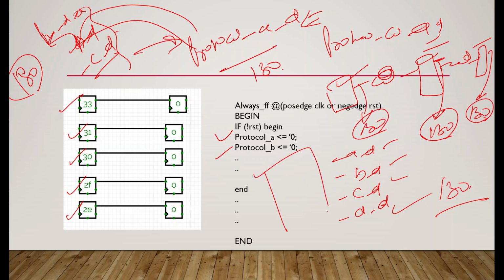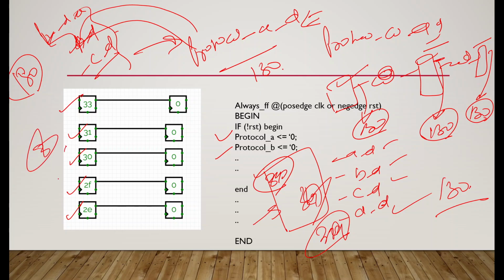So see the RTL size, like 390 declarations itself, the file size is too high. Compilation will become very hard, large, right? So you can see where code is very small, the data type declaration itself is 390 lines, and we are connecting it. Then we use 390 lines again, initializing 390 lines, 390 lines again. So for three times, right, for three stage flop, we are using 390 into 3, right? Around 1200 lines we are consuming.